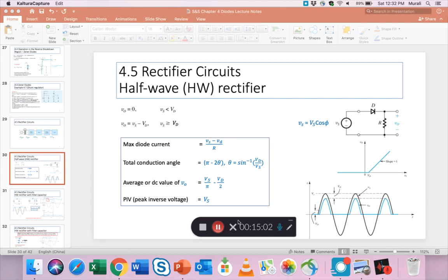So you can't take a little diode that you use in the lab to normally handle 5 volts DC. Maybe it can handle about 20 volts of AC reverse across it, but after that it can break down or cause other kinds of operation. So the peak inverse voltage is a measure of how much strength it has to oppose reverse biasing. As the AC negative cycle is fully applied to the diode, it has to withstand it and prevent the breakdown and current from being conducted, and the measure of that is called peak inverse voltage.